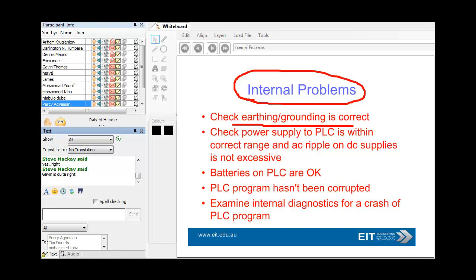But certainly, a problem that you can often have is the PLC manufacturer goes to great lengths to tell you about earthing or grounding or chassis. Please make sure that's done properly and your overall earthing plan is good, because you will find often this is the cause of very strange, unexplained problems. And the problem with earthing is that it doesn't just happen and you have an outright failure. You have an intermittent fault and then you don't know what the hell's going on. You find your remote rack drops out intermittently, you reset it and it's all running okay. Well, believe me, it'll come back again. That seawater pump will drop out again.